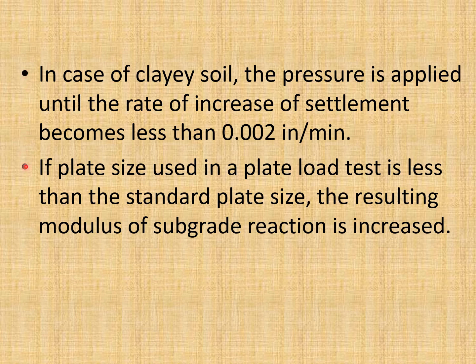Now this point is also very interesting. If plate size used in a plate load test is less than the standard plate size. What is the standard plate size? That is 30 inches diameter plate. So if plate size used in a plate load test is less than the standard plate size, the resulting modulus of subgrade reaction is increased.